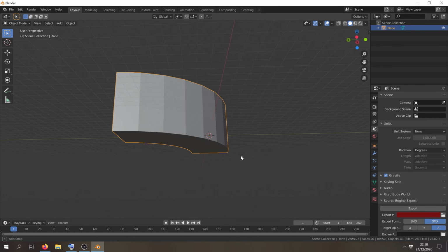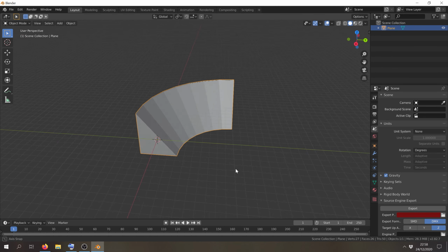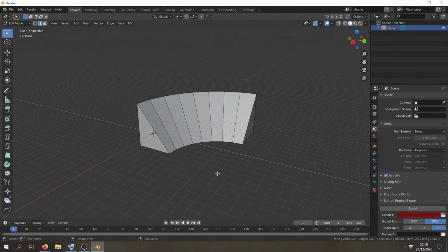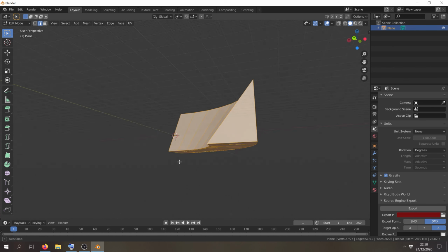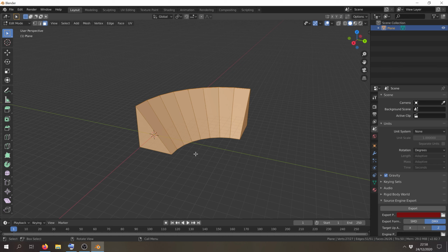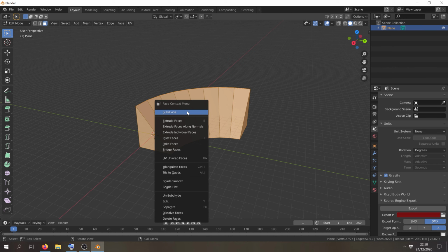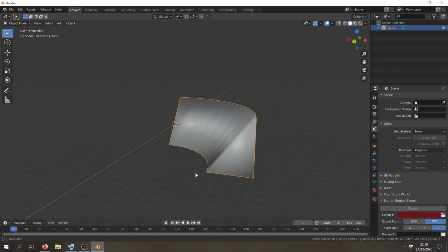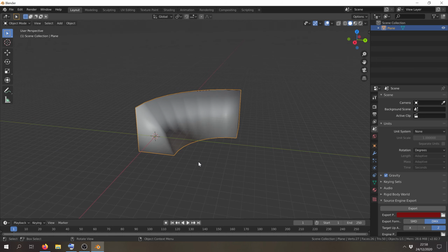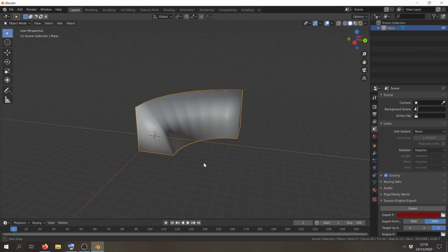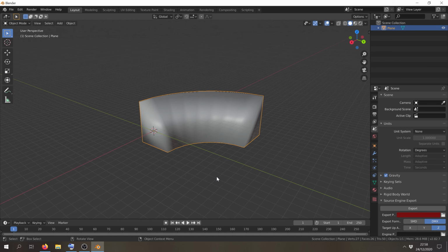As you can see, the lighting is not quite right yet. It's still flat shaded, and that's a simple fix. So we can go back into edit mode, press A to select all the faces. It helps if you're in face select as well. And then right click anywhere on your mesh and click Shade Smooth. As you'll notice, this now shades the ramp smoothly. So this basically tells Hammer how to compile the lighting on our map, on our ramp rather.